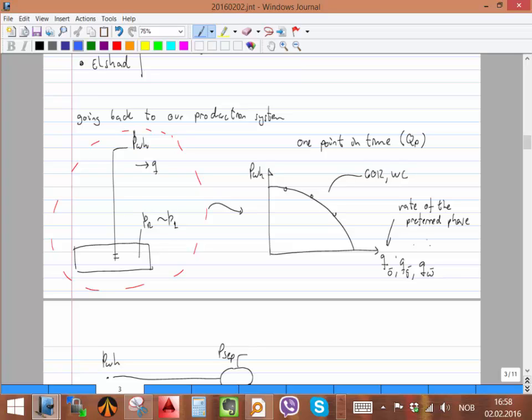So that's useful for all of you. Begin to see now which case, which production mode, A or B? A, okay? So in plateau, you can use this calculation. Actually, you can compute exactly the delta P of the choke that you need to produce that rate. So that's the beauty of the plateau. I fix the rate and I can calculate my delta P.